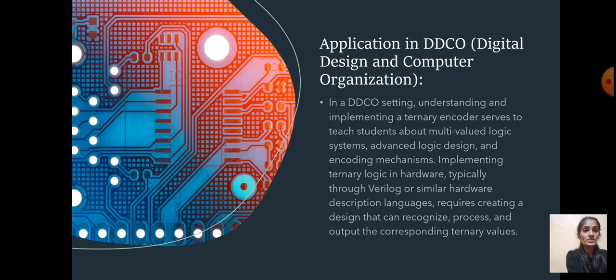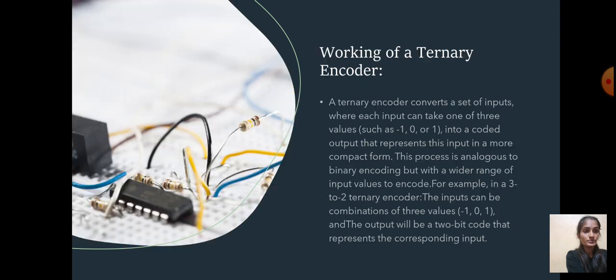Next, we are going to discuss the applications in DDCO. In a DDCO setting, understanding and implementing a ternary encoder serves to teach students about multi-valued logic systems, advanced logic design, and encoding mechanisms. Implementing ternary logic in hardware, typically through Verilog or similar hardware description languages, requires creating a design that can recognize, process, and output the corresponding ternary values.